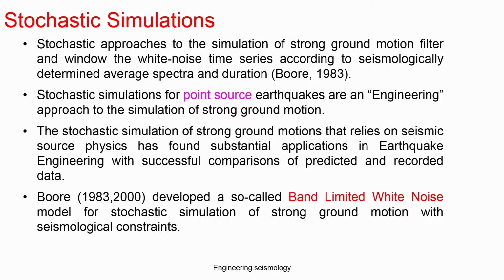The stochastic simulation of strong ground motions that relies on the seismic source physics has found substantial application in earthquake engineering, with successful comparison of the predicted and recorded data. So, Boore developed this stochastic simulation model, and he found there is good application in engineering seismology. He also validated his model by comparing really recorded earthquakes with the simulated earthquakes.